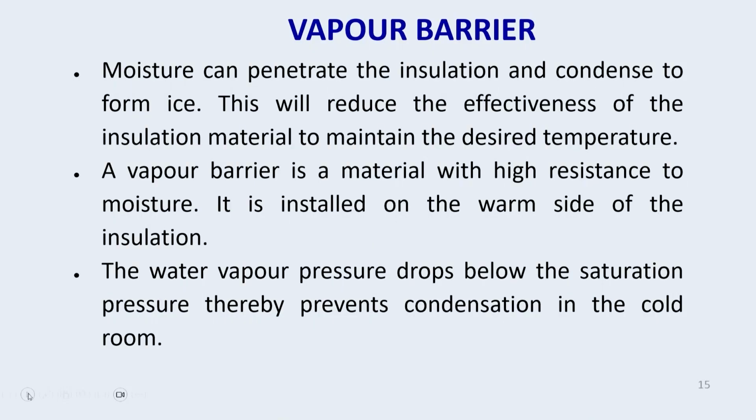Moisture can penetrate through the insulation and it can condense to form ice. So what happens when we have such a situation? The effectiveness of the insulation material will be reduced, and it will not serve the purpose of maintaining the desired temperature. As much as possible, moisture should not enter into the cold room or cold store.